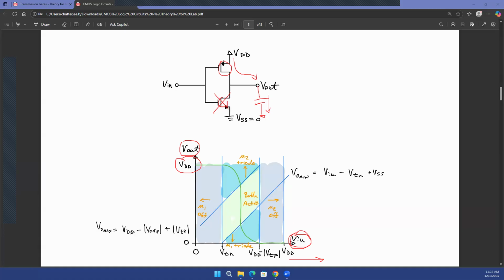If you think about the PMOS transistor as a switch, the top of the switch is VDD, and the bottom of the switch is also connected to VDD when the capacitor is charged. So only because you have capacitive loads, and not resistive loads, in digital circuits, the argument that digital circuits only consume power when switching holds true.